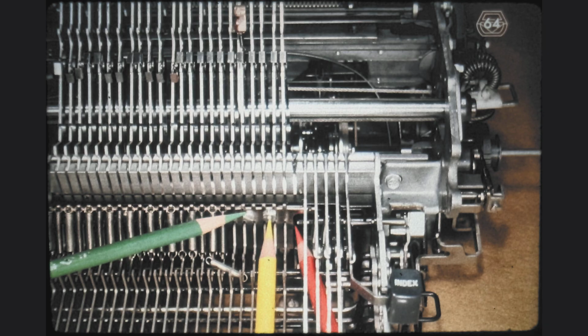If you take a close look at the rear portion of the interposer, you will notice that the bottom of the compensator tube serves as the upstop for the interposers when they are at rest. Since these screws are used for the adjustment of the height of the interposers, this is the most important adjustment of the keyboard. As a matter of fact, it is the fundamental adjustment of the input section. The yellow pencil indicates the tail end of the screw and the nut which hold the compensator tube assembly together.